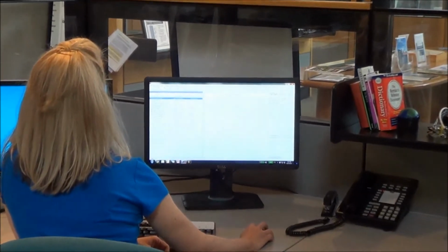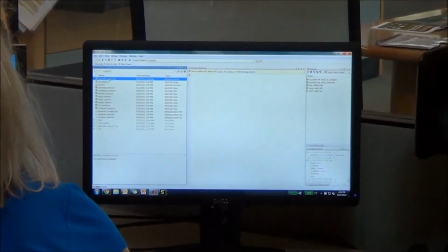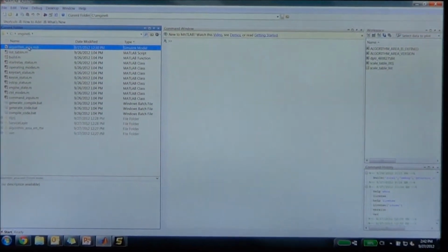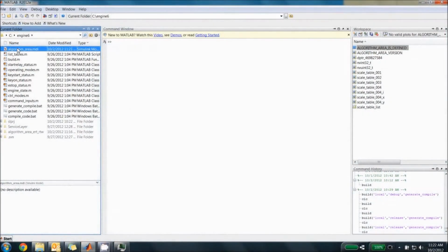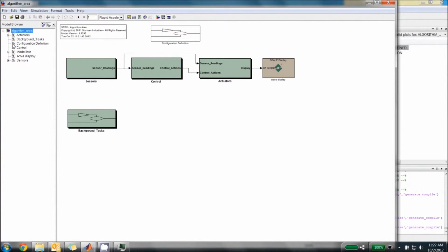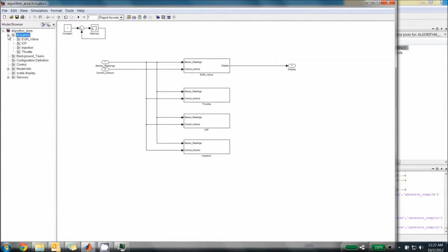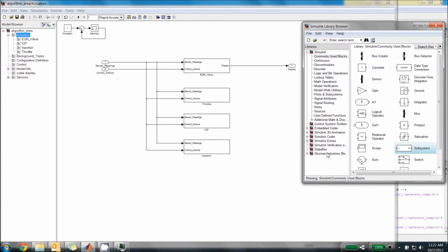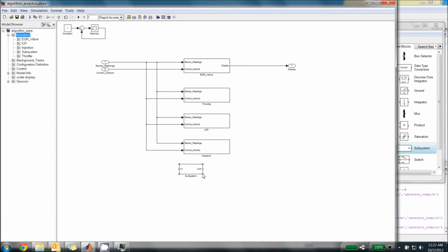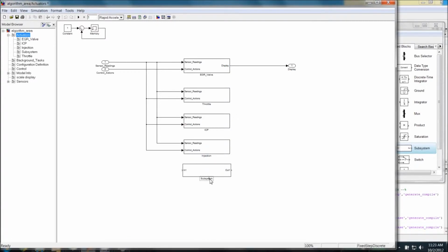In this example, we add a pulse width modulated turbocharger actuator to an existing engine control model. After opening the Simulink model and the block library, navigate to the desired location for the new device. In this model, actuators have been grouped together at the model's base level for readability. The new turbocharger will be implemented as a subsystem inside this block. Start by dragging a subsystem block onto the model from the standard Simulink block library. Inside this new turbo subsystem, build up the turbo components.